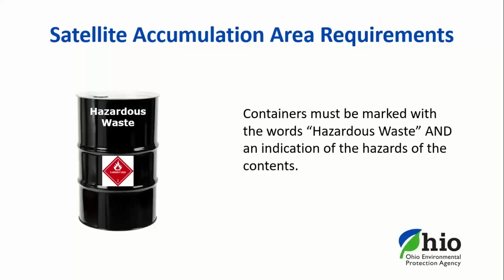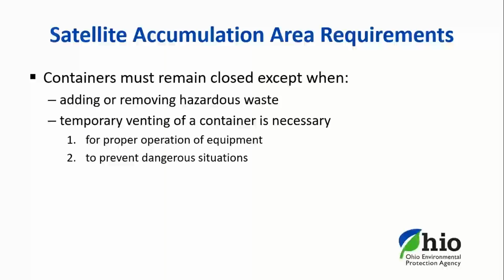Marking and labeling requirements apply to satellite containers, so they need to be labeled as hazardous waste with an indication of the hazards. The satellite containers need to be kept closed except for when you're actively adding or removing hazardous waste, or if you need to temporarily vent that container, maybe to prevent a buildup of pressure.